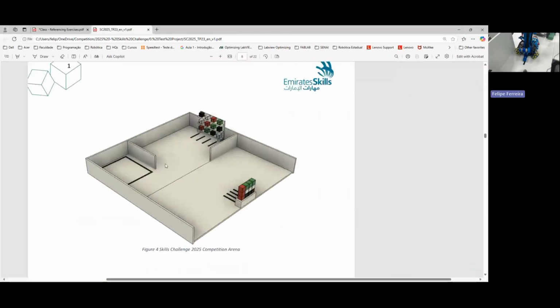Okay. So my robot is going to perform the same task many times. Starting from the initial point, go, take one cube, deliver the cube, come back, go, many times. Every movement my robot does, it gets an error, and this error will accumulate. Once in a while it is good for me and for my robot to reset this error, to make this error 0. To do that, we're going to reset the robot position.